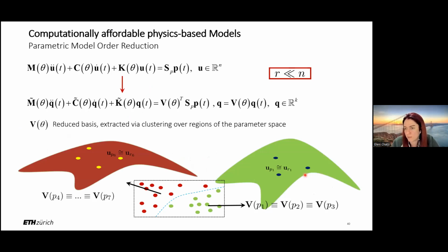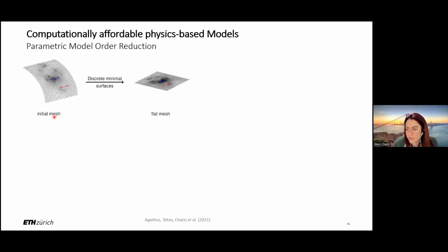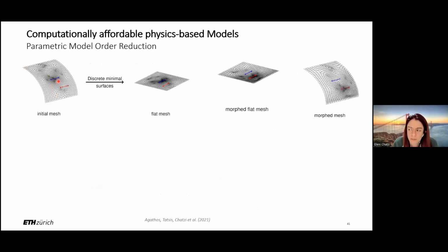This is a parameterized problem because the flaw is parameterized. We have different lengths and locations of this possible damage. And so we have a reference model of this fuselage structure that we try to build in a parametric sense, as I mentioned before, but in a reduced sense as well, so that it can compute in real time. There are a number of numerical manipulations that we have to do to achieve these tasks for curved and thin geometries that include a crack. And for those that are interested, I can refer to these stages, which rely heavily on the concept of mesh morphing, later on in the question section.